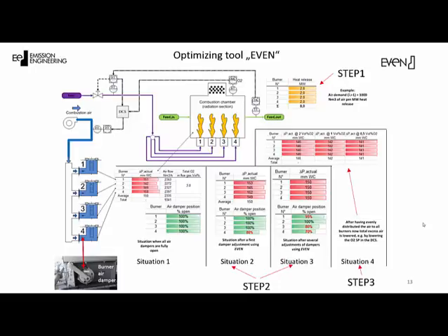Once uniform air distribution to all the burners is achieved, and only then, the total excess air can be lowered. It's clear that, without proper air distribution, any excess air adjustment with the help of the oxygen analyzer will be pure luck or fake.